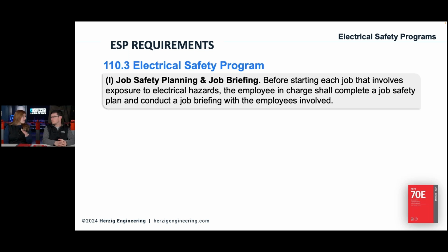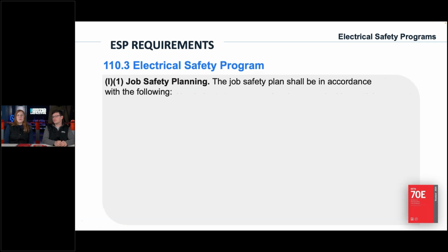So when do we need to do these? Before the start of each task. Anytime there's possible exposure to electrical hazards, you should be having people stop and complete a job plan and talk it through with those involved. Okay, so what goes into a job safety plan?